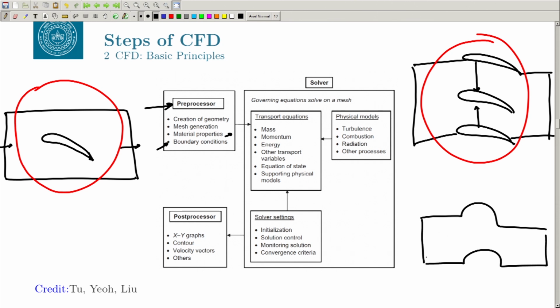So, a good approach would be, if you have, let us say, 100 points on top, then you have 100 points on the bottom also. If you have 50 points here, then you can have 50 points there also, so that they conform to each other. So, this is a conformal periodic system. Of course, if you do not have that, you can still interpolate, but if you know that you are going to apply a periodic boundary condition on top and bottom, then you can accordingly define your grid points and decide your computational domain.